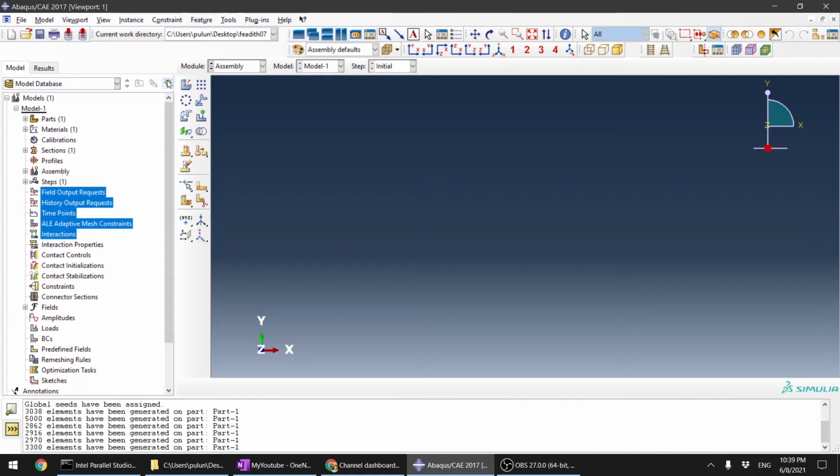You click here. So basically, the part is just part. It's basically things that you have in your workshop, right, or in your model, in your file. But when you do simulation, what you simulate is what's in assembly. Okay, this is what you're simulating. So you can have many parts, maybe in some cases you have so many parts, like 1,000 parts, but you don't want to simulate these 1,000 parts all together. You want to make an assembly of several parts. So you just need to choose things that you want to simulate, and assemble only those.